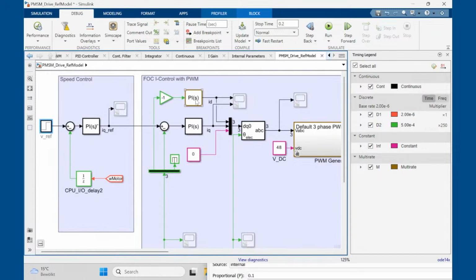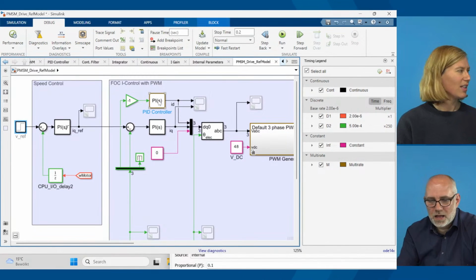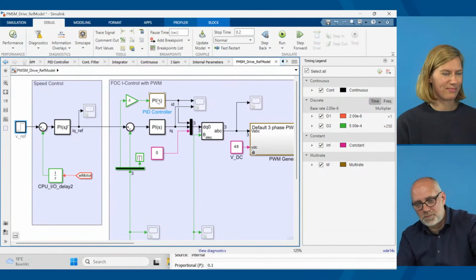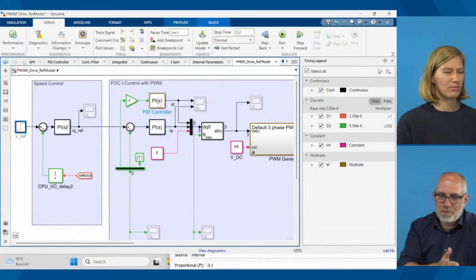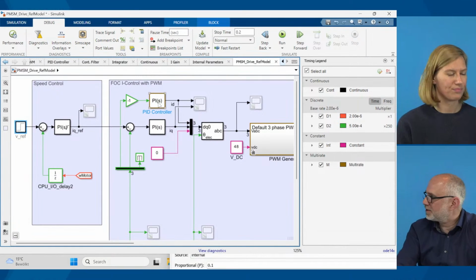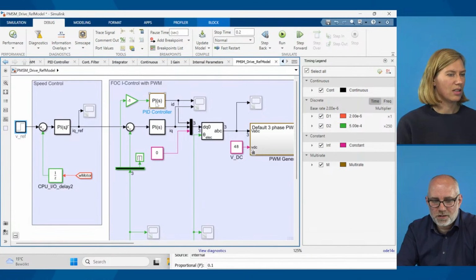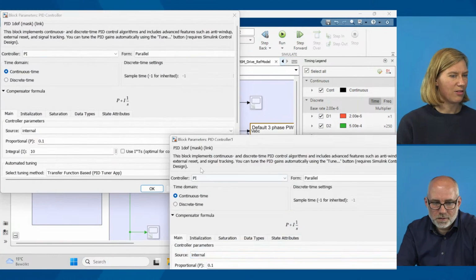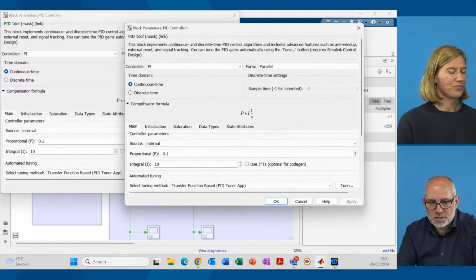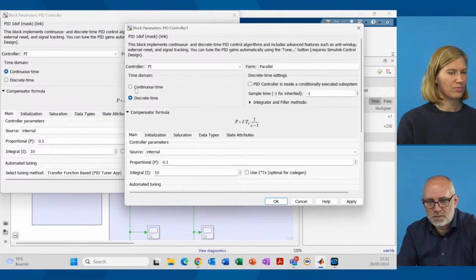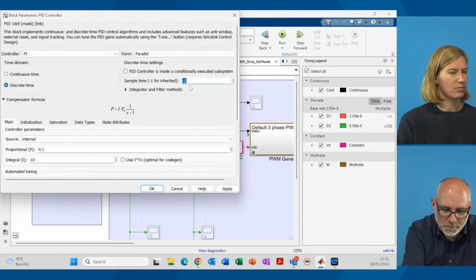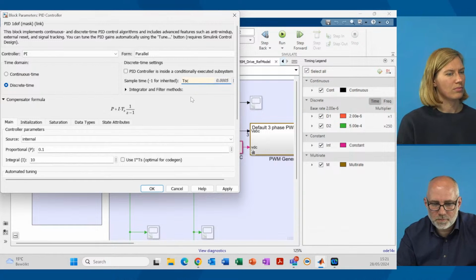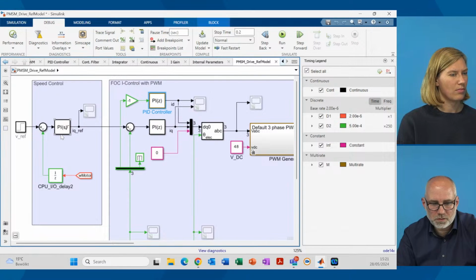We still have the continuous PI controllers. That's also something I would correct: let's go really to time discrete mode and not mix things with discrete sample time but continuous description. You need a solver there, which does not really make sense. So we can go in here and set all of them to the same settings with the same sample rate. We can just click here on discrete time instead of continuous time and use the sample rate TSC, which is the 500 microseconds also here. So we have 2 of the controllers, and a third controller here.